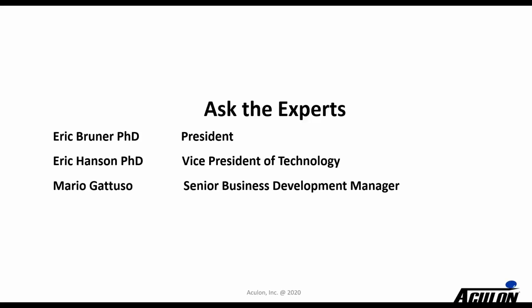That's a good question. On stainless steel, we are very durable. As a thin coating, our durability is usually a function of the underlying substrate. So anything that would abrade the underlying stainless steel or chemically etch it, maybe a high caustic solution, can remove or damage our coating. Teflon does have some advantages in that it's really thick, so you may be able to abrade some of it and still have something underneath.